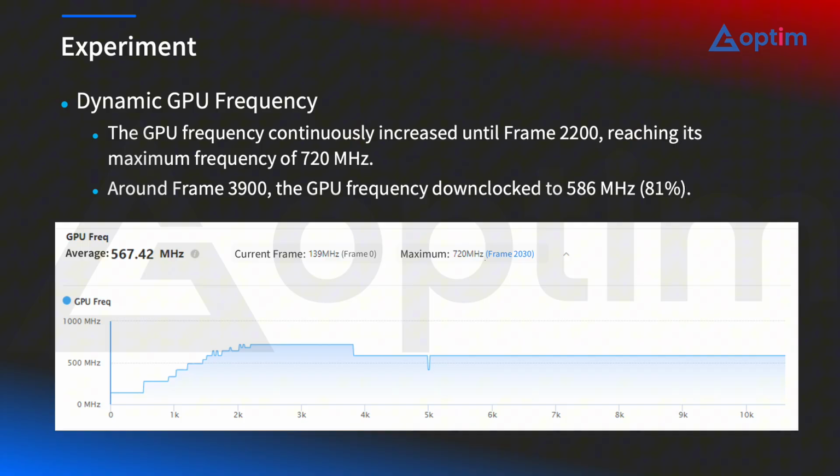In the early stage, when overdraw is still low, per-frame clocks are also low, and the GPU does not need to run at maximum frequency. As overdraw increases, clocks continue to rise. However, once the GPU stays close to its maximum frequency for a sustained period, clocks continue increasing and GPU pressure becomes extremely high. At this point, thermal or power constraints trigger frequency throttling, which leads to a sudden FPS drop. So in summary, FPS, GPU operating frequency, and per-frame clocks are tightly coupled and influence each other directly.